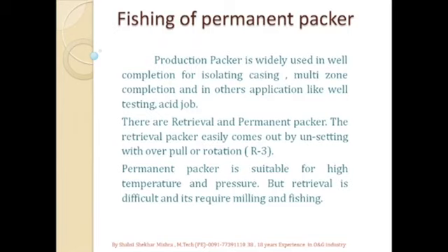Production packers are widely used in well completion for isolating the annulus or the casing. By isolating the casing, we save the casing from the corrosive fluid of the well. Also, in multiple zone completion we straddle the zone with a packer, and in other applications like well testing and acid jobs.